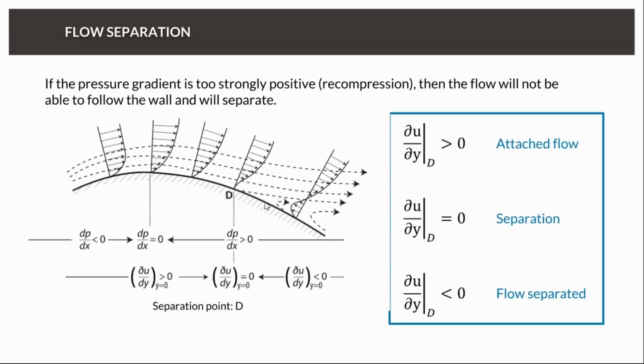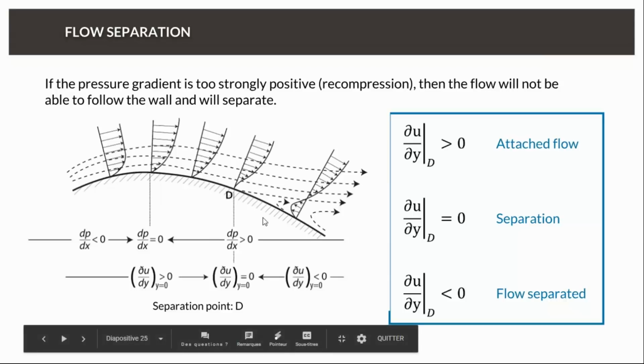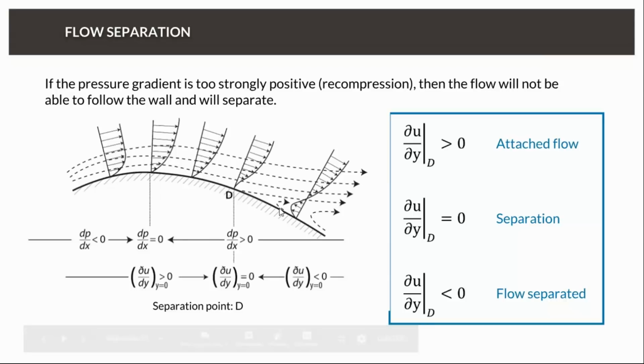You could imagine, as an analogy, a cyclist who would see a street that's going up with more and more slope. So here the pressure is getting higher and higher, and the boundary layer will have more and more difficulty to counter it. In the regions where we have a positive gradient, there is a risk that when the boundary layer is too weak, you will see that there starts to be return flow and we will have flow separation.